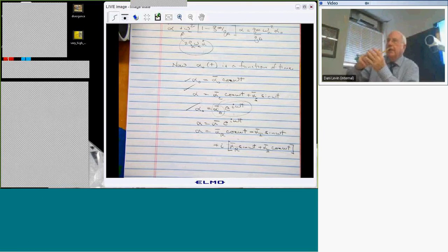If I have an airplane, I have a wing, right? I could think of orienting the airplane, and the twisting always takes place relative to the fuselage. So I'm changing the fuselage angle relative to the flow. That's alpha naught. And then alpha itself is the twisting of the wing relative to the fuselage. Does that make you a little happier? Yeah. Okay. Gee, you people are tough.